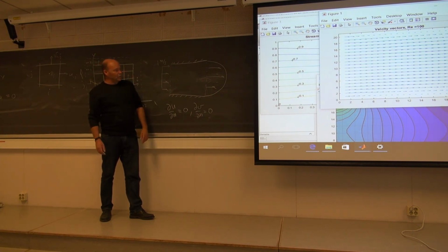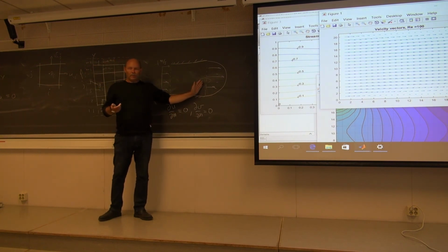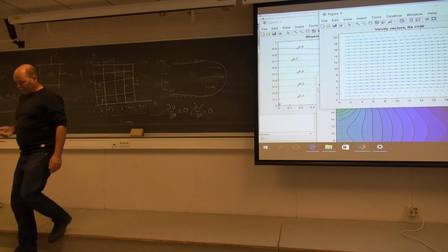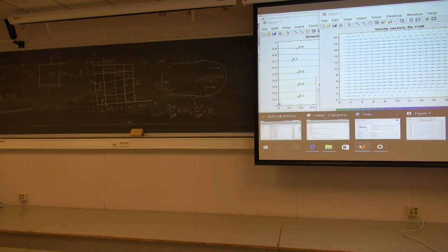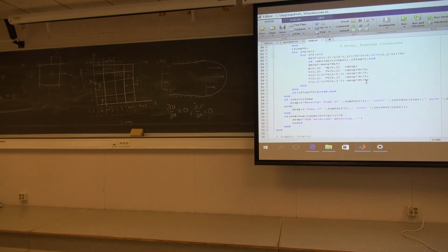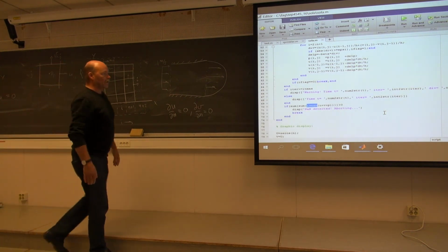Of course, something is going to explode numerically in the end. The second one exploded quite rapidly, meaning it was unstable. It detected what's called not a number in MATLAB. I have a test in the code checking if any numbers are not a number. I just add all these solution matrices together and check if some of them is not a number, and if so, you just break the simulation.